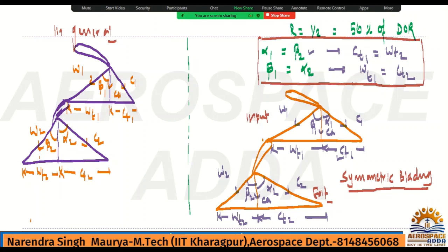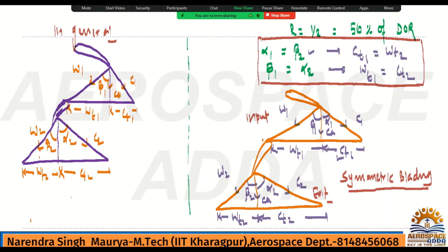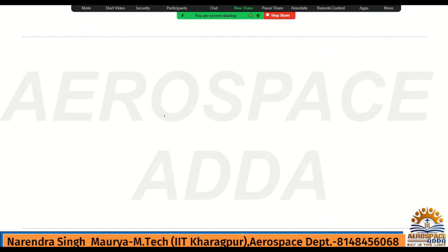The same velocity triangle you can draw in this way also. So what is common in this velocity triangle? Obviously the base is common, that is true, but CA, the axial velocity, is also common for both triangles, inlet and exit, in terms of the vertical height. And horizontally, what is common? U, the blade speed or rotational speed. Because u1 is equal to u2 and that is constant, so u1 equals u2 equals u, which I already discussed in my previous lecture, so no need to go into that. I just want to draw this triangle in this way also, because in GATE many questions are given this way. This is constant, and this is nothing but u.